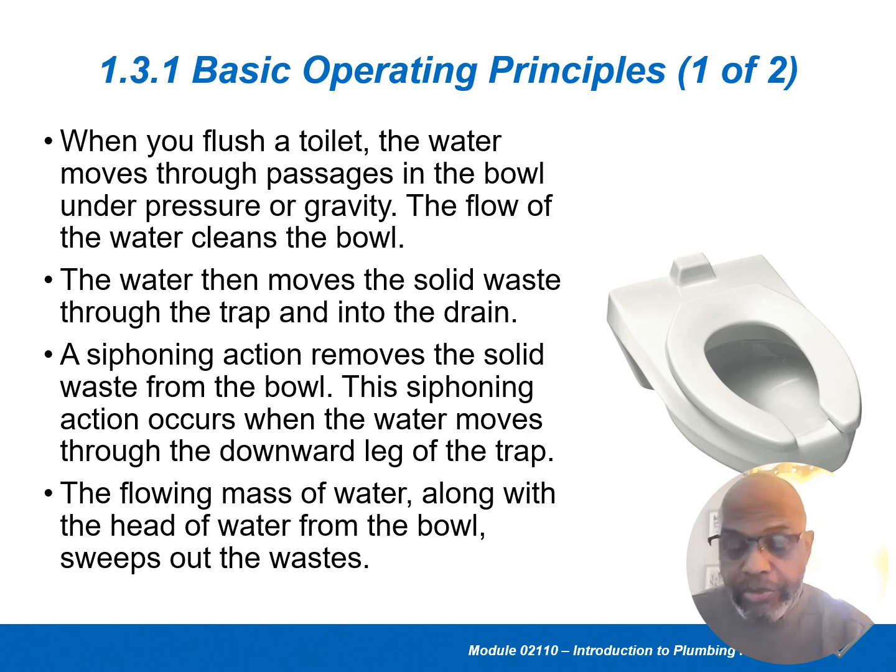Matter of fact, even residential, it's a little bit different how you do it, but basically for residential, you're adjusting the height of the water inside of the tank. And in commercial ones, there's a diaphragm inside of a fixture that you're adjusting that will cause it to close the valve and stop the water flow.